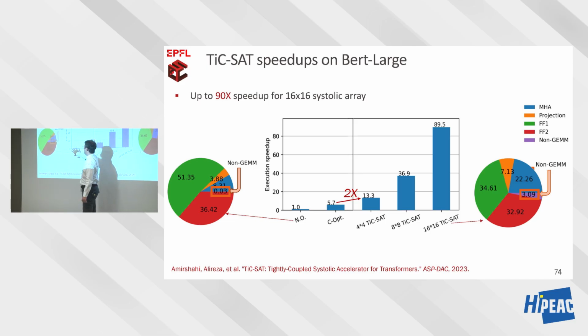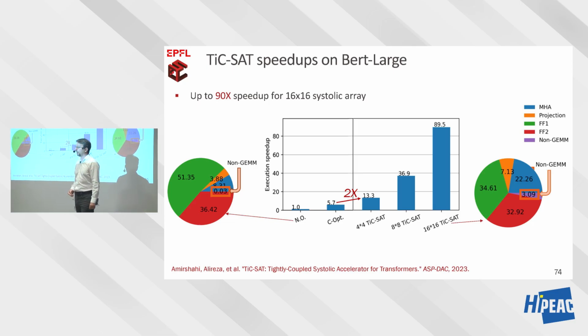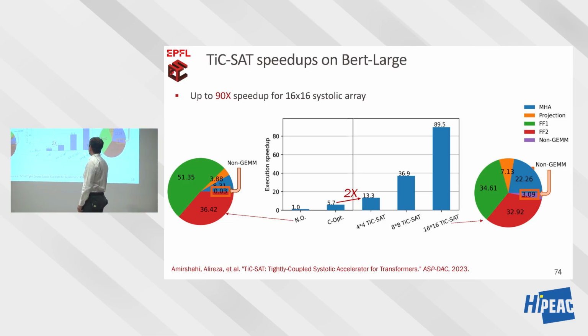This is the naive implementation of the transformer code. Here we try to optimize as much as possible using tiling, using data reuse, but still at the software level. And here we started to accelerate in hardware. So with 16 multipliers and 16 adders, we already had a 2x. I would say that these are 16 multipliers and adders well spent. And if we have more area, we can invest more, we can just scale up these operations.